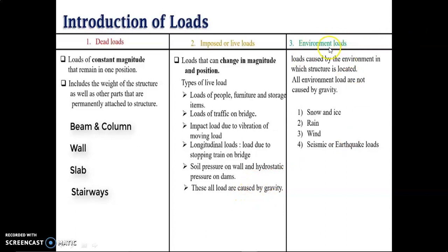And the last one is environmental loads. These are loads caused by the environment in which the structure is located. All environmental loads are not caused by gravity. So these are the environmental loads: snow, ice, rain, wind and seismic loads.